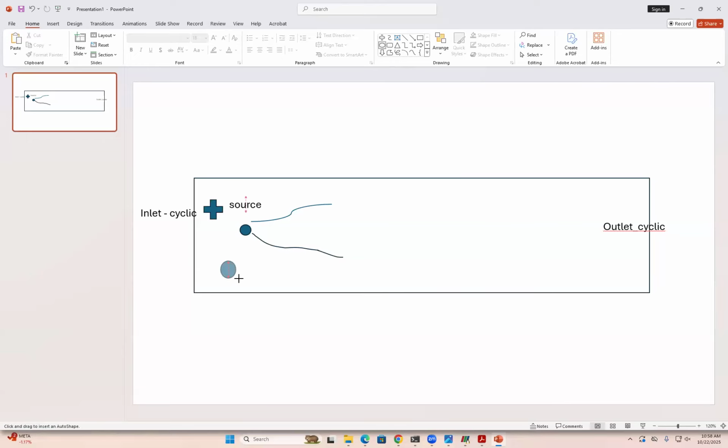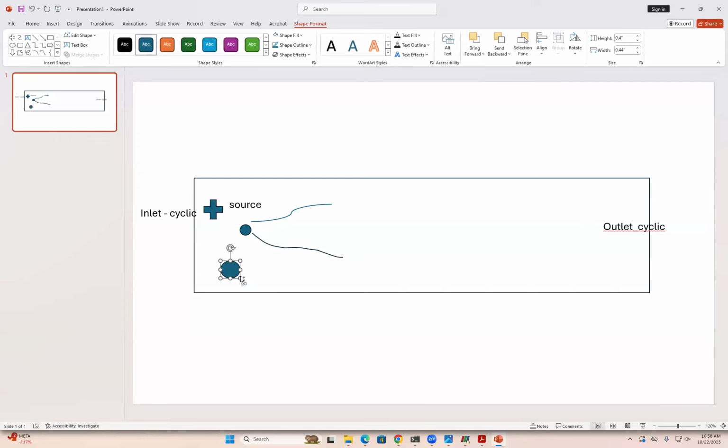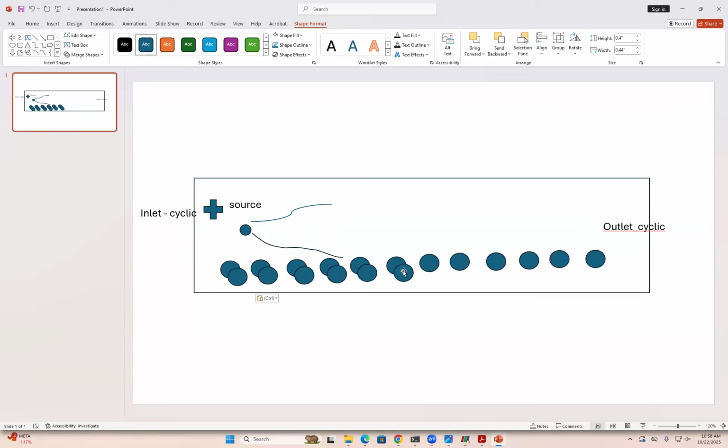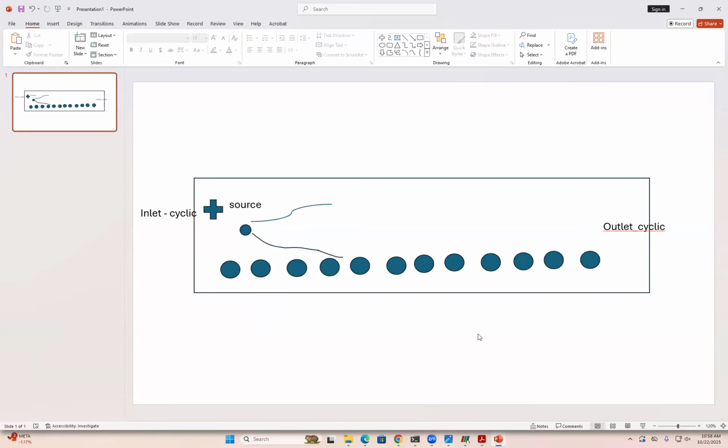In the second case, I would like to put some kind of bead type of thing that we need to subtract from the geometry. Yes, topoSet typically means subtracting something from the domain. Then I would like to run a simulation with laminar, then turbulent, and see the effect.